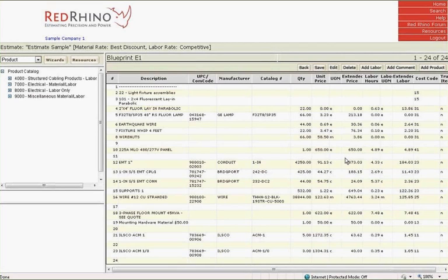This is the takeoff input page. As you select materials from the box on the left, the program adds them to the box on the right. Our example shows some materials which have already been input for this project. Let's say that your project also includes a 2-inch conduit run, and you need to include this item. Watch how easy it is to add 2-inch EMT conduit with 3 3/0 and 1 number 6 ground.